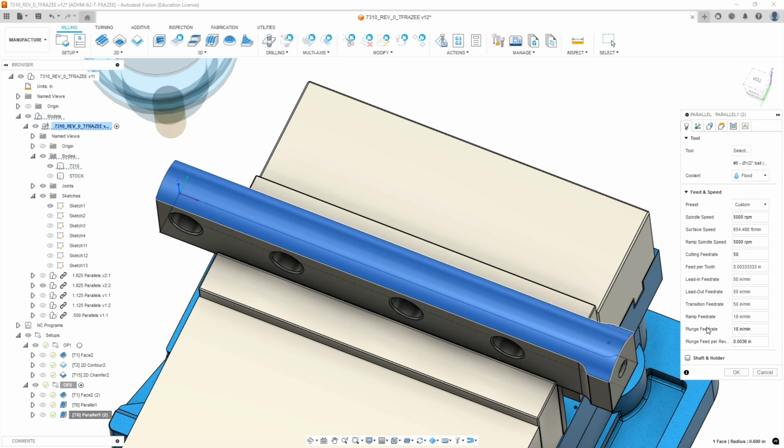And then our ramp rate feed rate, and our plunge rate on a surface cut is actually sideways, except for the very first move. So we're going to go 50 inches a minute on that one. Now, it's really important that you remember, if you do a routine after this, to slow it back down to the defaults for other things.